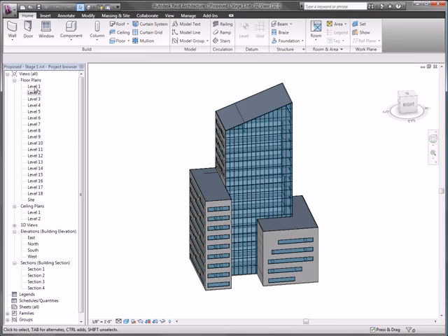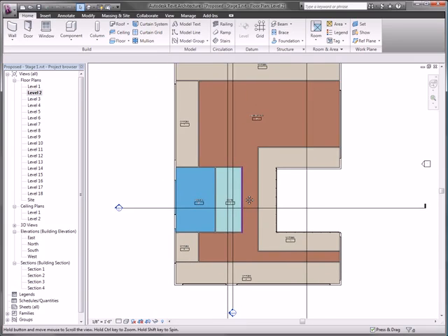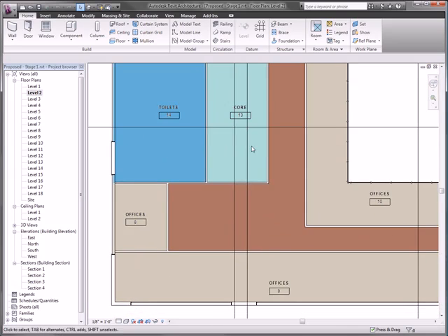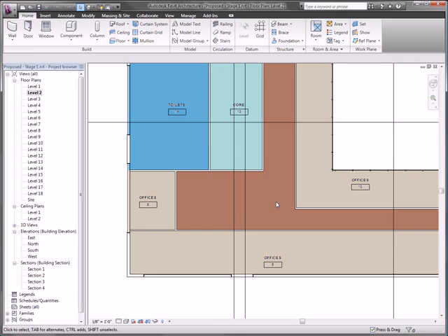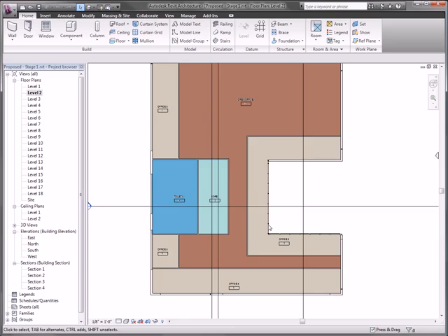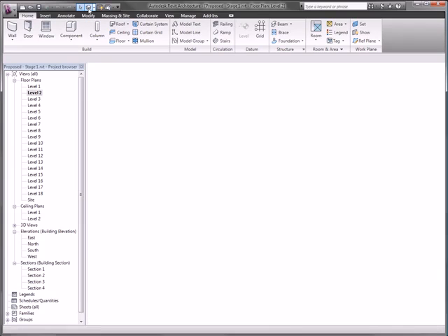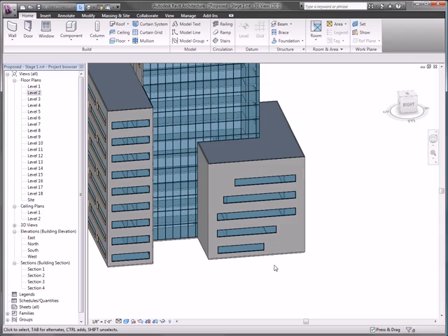So you'll see that I haven't included all of the interior partitions and I haven't put any interior doors in yet. Although my Revit model is always intelligent, here I'm treating it a bit like a 3D bubble diagram. And the windows are also simplified. I'm not worried yet about every single punched opening and exactly where it is on the facade. I'm mostly interested in the ratio of glass to solid wall.